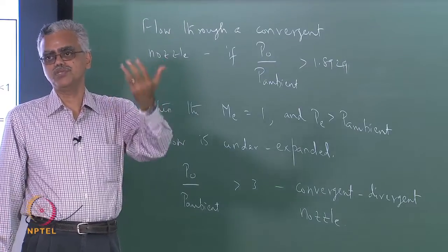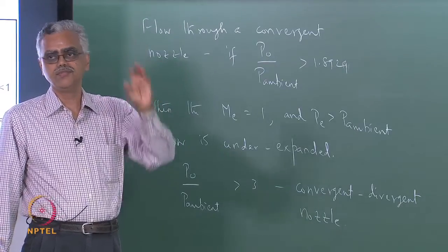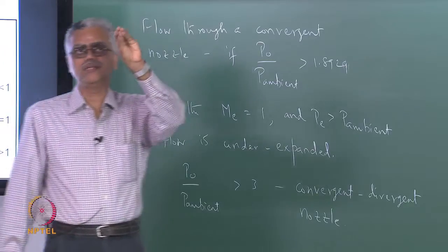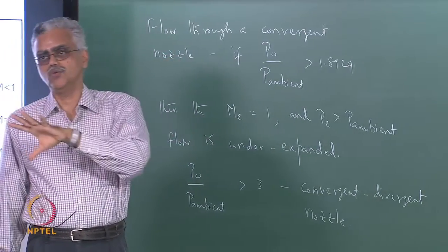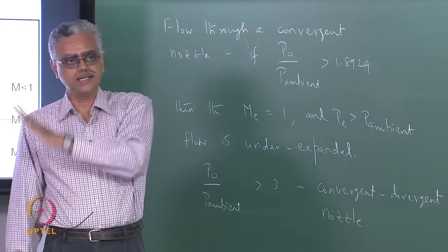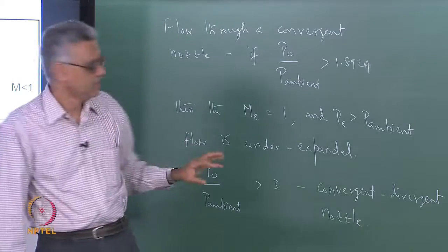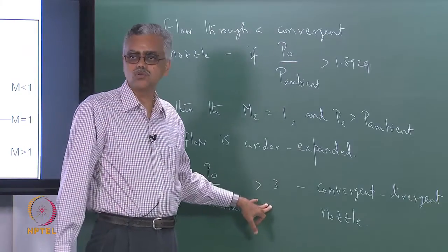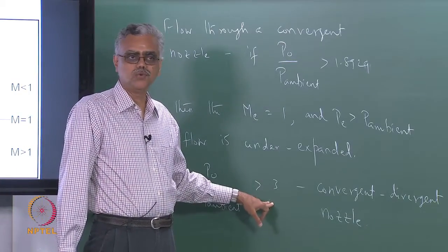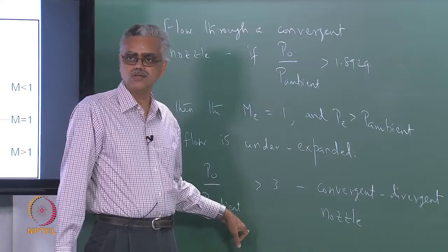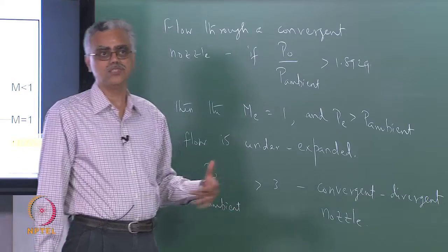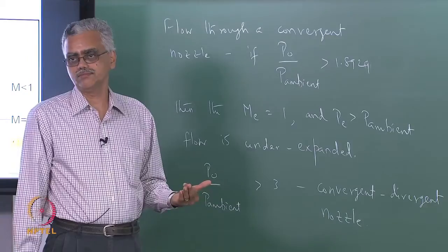That means the stagnation pressure generally increases by a factor of 30. There is no change of stagnation pressure in the combustor, and then we extract work in the turbine. So, the stagnation pressure just upstream of the nozzle, because of the work extraction in the turbine, will probably be reasonably close to this value, which is why we use a convergent nozzle in an aircraft engine, whereas we use a convergent divergent nozzle in a rocket.